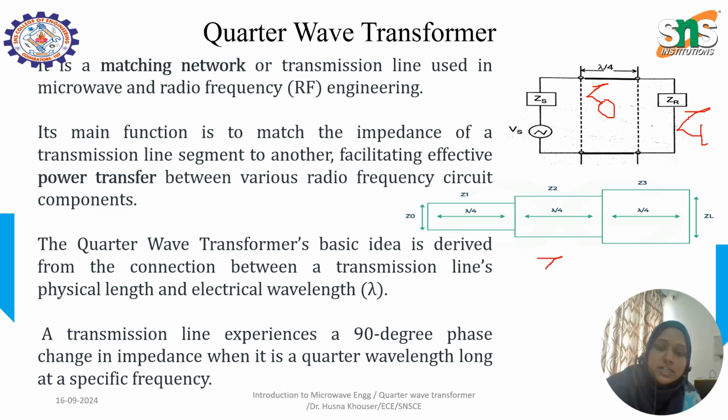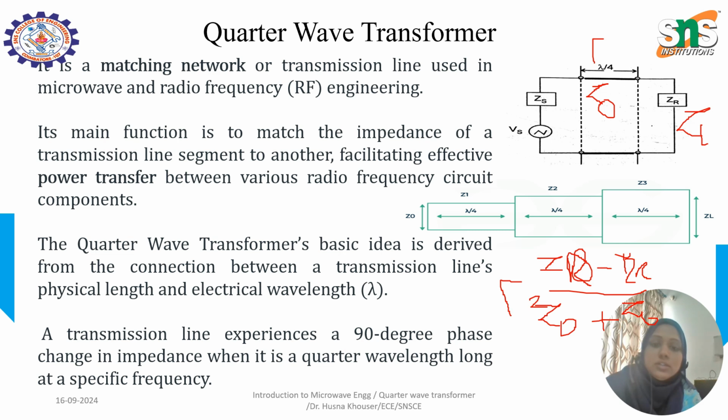We know this law of reflection. Recall this equation: the reflection coefficient is (ZR minus Z0) divided by (ZR plus Z0). Now, in between, we are going to insert this matching impedance circuit, which we call the quarter wave circuit.